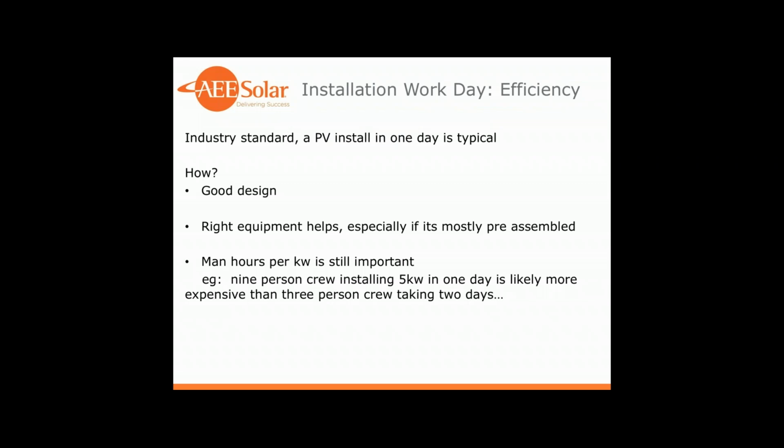Well, in that case, if it's a smaller site, that could still be a waste of money. So you want to make sure that you're thinking about your man hours per kilowatt. The example I list here is a 9-person crew doing a 5K system in one day. That's actually worse than a 3-person crew taking 2 days to install that same system. So just make sure that you keep the right balance in mind.